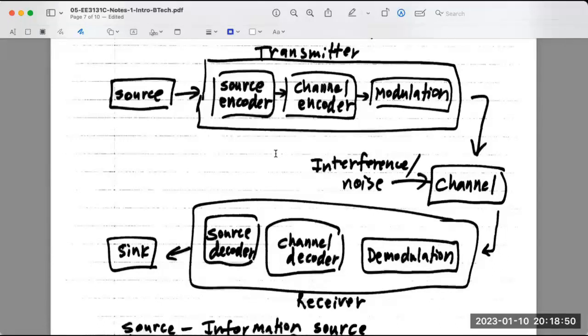Actually, you guys have figured out, in this world, there's no free lunch. You don't get something for nothing, right? You've got to pay a price. The price of channel coding is a little bit of redundancy. So channel coding adds redundancy back, but it gives you robustness to noise. It allows you to do error detection and error correction. I'll show you in a minute.